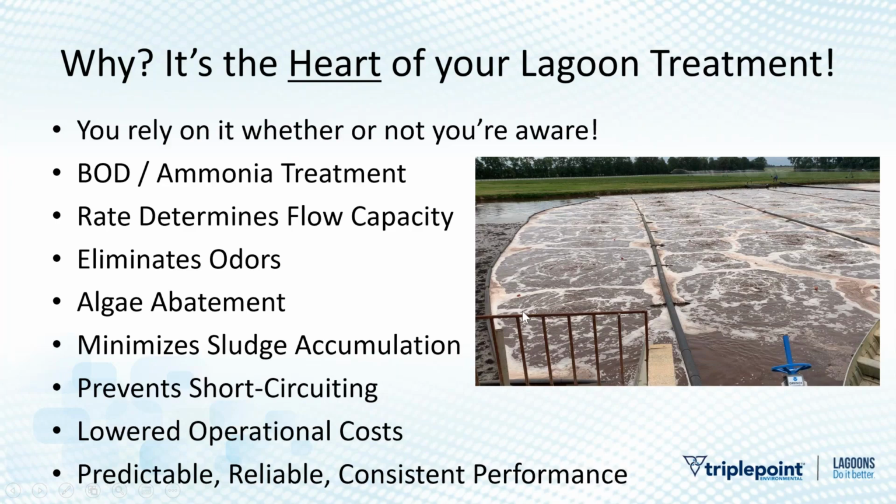With aeration, you can lower your operational costs. So if you have an old aeration system that was broken or maybe was designed in the 1970s and is not very efficient, putting more efficient aeration in your system can actually lower your energy spend by up to maybe 50%. So it's pretty powerful. And overall, aeration is the key source for predictable, reliable, consistent performance. Across the board, if you have aeration in your lagoon system, it'll account for about 80% of the money your town's spending to treat wastewater. That's just where most of the energy goes. And most of the energy goes there because that's what's doing most of the heavy lifting.